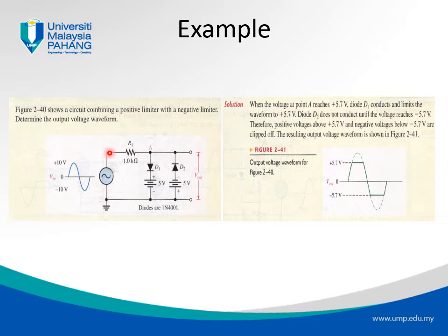The voltage will go across R1 and then arrive at node 1. It has two possibilities, whether to go into D2 or D1. It can only go into D1 because D2 is in reverse bias, so it cannot go into D2. But when it goes into D1, in order to cross D1, it has to pass the voltage bias of the diode, which we can consider to be 0.7.